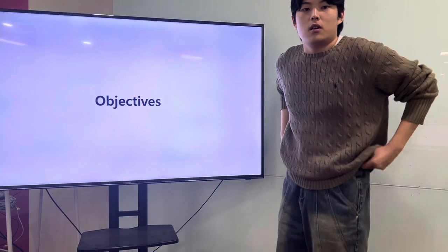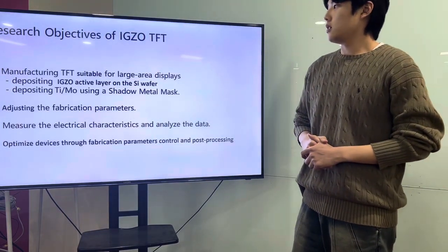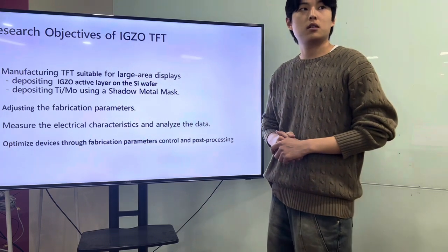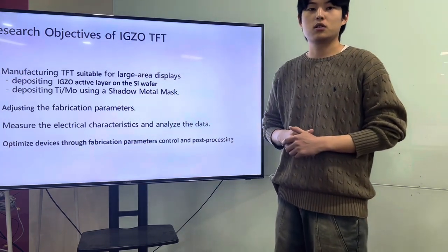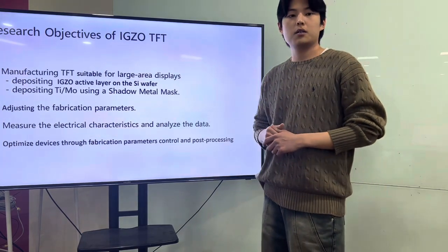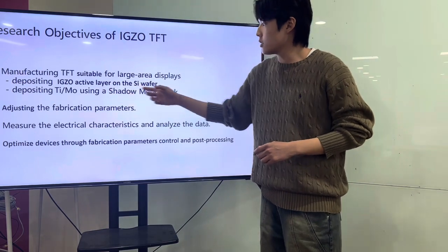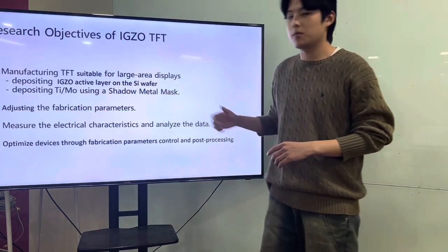Next are our experiment objectives. First of all, taking advantage of these characteristics, our plan is to make IGZO TFTs suitable for large displays. We will deposit the IGZO active layer on the silicon wafer, and then deposit a Ti/Mo electrode using a shadow metal mask.